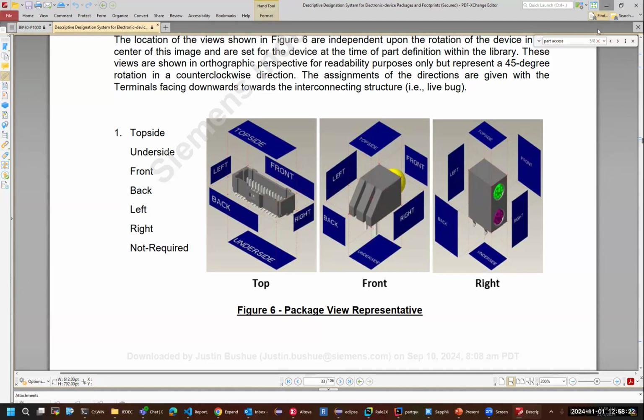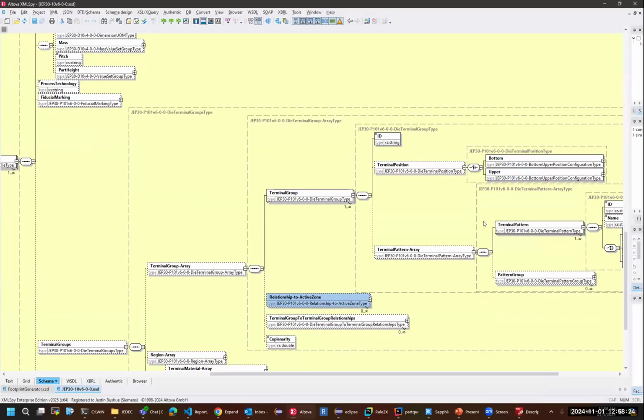So if you take a chiplet and it has bumps on the underside, or bumps on the top side, whichever way you want to have it. Let's say it's bumps on the top side, and you flip that in order to do the assembly, then so be it. You flip it on the assembly. But at the time that you define the chiplet, it's not on an assembly. At that point in time, the bumps are on the top side.